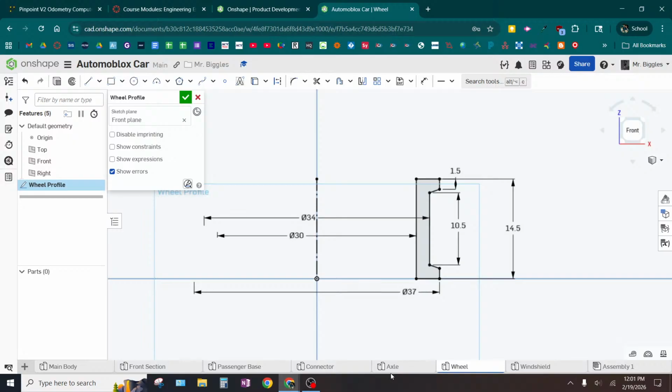For measuring the outer diameter, you'll use the big fat teeth on the bottom, but when you do it, I would go at an angle, so that you are grabbing it around its fattest part, guaranteed 100%. So I have mine at an angle, you see that? So I can get them in there, so I'm going around the fattest part guaranteed.